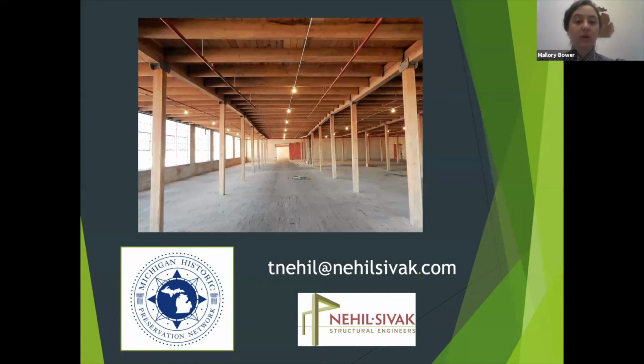I know some people do. I usually don't try to do too much scraping or planing on the material in the building, just because it's still such a small little window and it may have too much stuff goobering up the appearance of the grain. So I will go to taking small samples, something about the size of your little finger, let's call it, and take it from a discrete location. And then I can look at that under the microscope or with a little handheld magnifier, and I can do a much better job that way than messing around with planes or scrapers in the field.